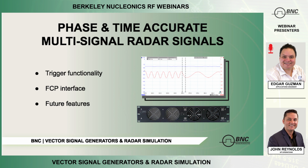One of the features that you see on a lot of vector signal generators is the FCP. It's the fast communications port. So specifically on our 875, it allows you to stream IQ data directly into the unit. That's one of the options that we allow. So you're able to change your IQ signals on the fly and directly send them. So whether you had them generated from some mathematical simulation software, or you just had them from a previous simulation, you're able to give them direct.